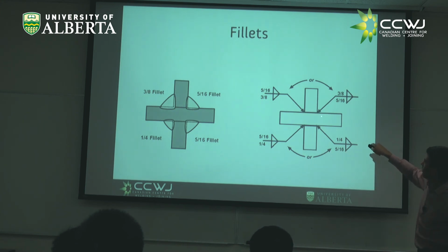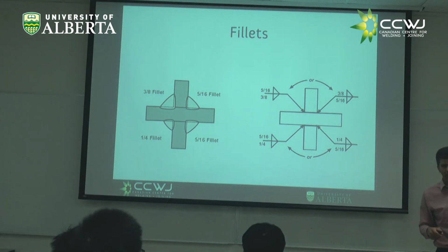The other side here, not the other side here. Okay? So the other side. And this is fillet 2, right? And it says 3/8. That's the leg. When in a fillet they give you a 3 millimeter fillet or a 5/16 fillet, that means what the leg is, right? That's the unit of measurement of the metric of the fillet.